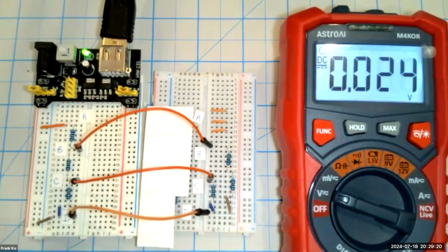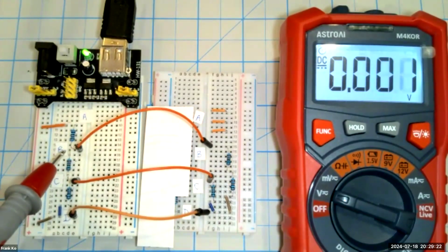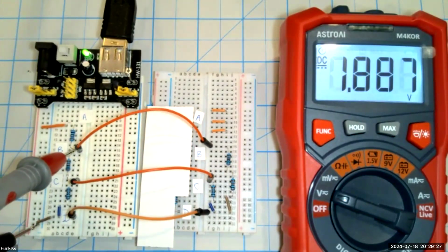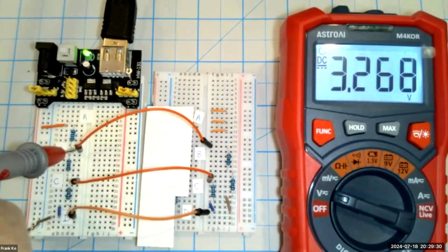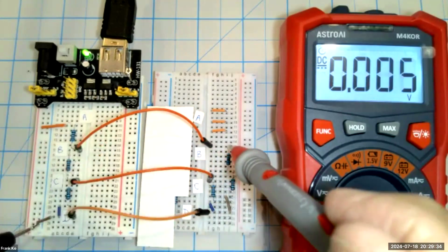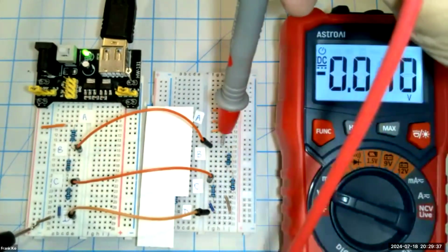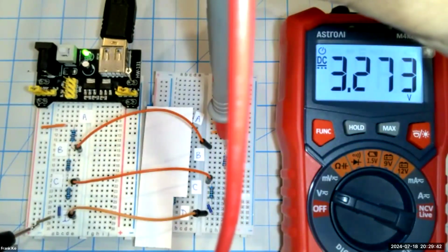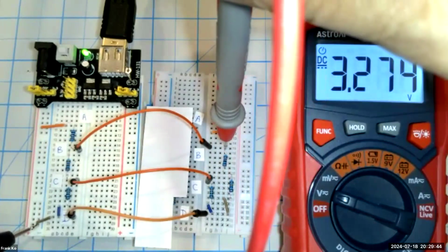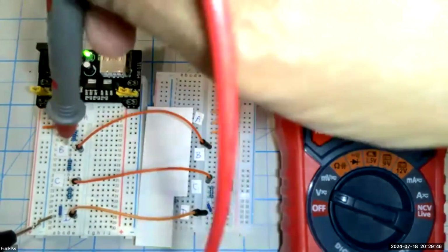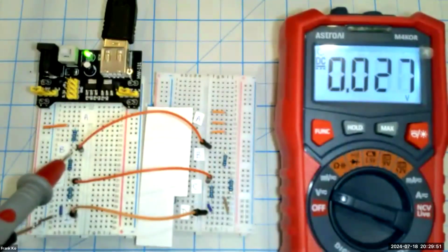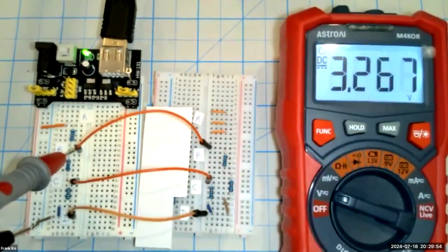And as I've said, we were able to enjoy 4 volts here before at point B. I guarantee you we will not see 4 volts now. And we don't. If we don't have 4 volts at point B now, we don't have 4 volts on this side at point B. No, we don't. It's 3.273. So something's dramatically changed. We previously had 4 volts over here. Sorry, let me move my hand. We previously had 4 volts over here. We now have